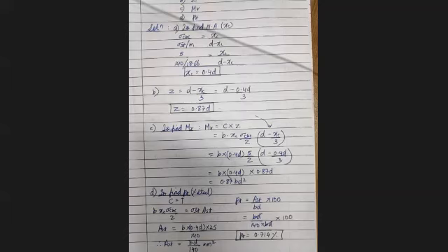Then the fourth step, the last step, is find MR. The MR equation you already know. MR is equal to T into Z if it is under reinforced, and MR is equal to C into Z if it is over reinforced. So I've just explained the procedure to you. Make a note of it. Whenever we solve a problem to find out the MR, you are going to follow this procedure.